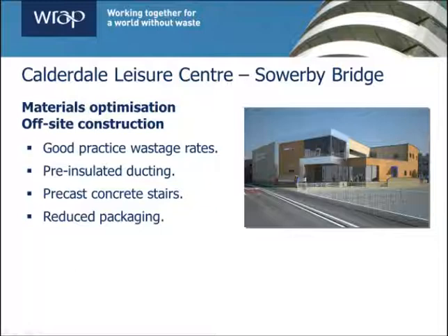Rather than casting concrete stairs in situ, staircases were cast off-site, thereby eliminating the formwork that would have been required. Packaging waste was also reduced, particularly for bricks, as these were delivered with metal strapping rather than the normal strapping, polythene wrapping and pallets, thereby saving nearly £1,000 and, just as importantly, 6 tonnes of waste.